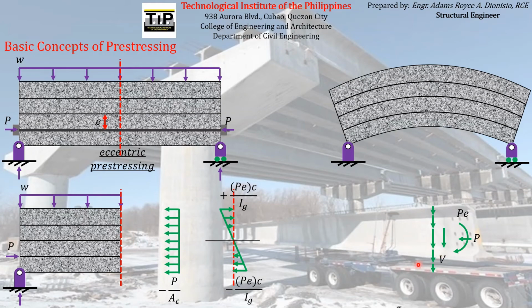And we assume that the shear stresses acting at the cross-sectional area are constant with the magnitude of shear average. But again, in reality, it's not constant. It varies with the maximum magnitude on the location of the centroid and then diminishes as you go to the top and bottom fiber, most especially if the concrete has a rectangular cross-section. And in addition to that shear force, another thing that this applied load produces at this particular cross-section of the beam is the bending moment.